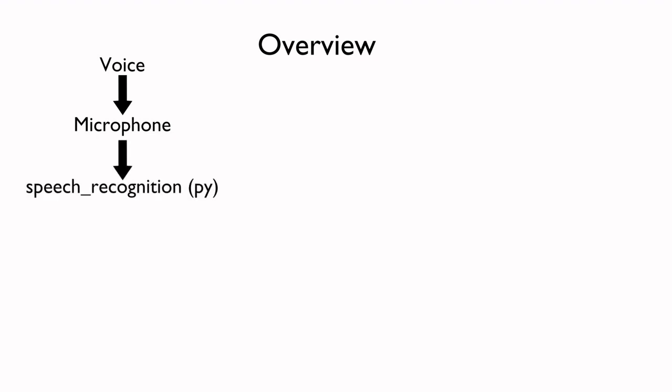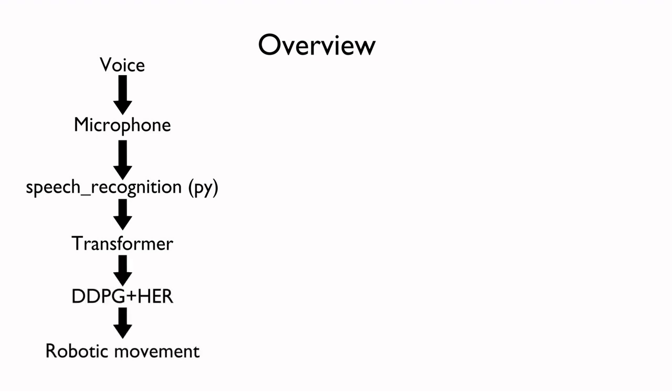The robotic model as well as the transformer are trained separately. We then combined the two models, where the voice is recorded by a microphone, converted into text by the Python package speech recognition, translated to a command vector via our trained transformer and then executed via our trained robot arm. The result is demonstrated in the following.